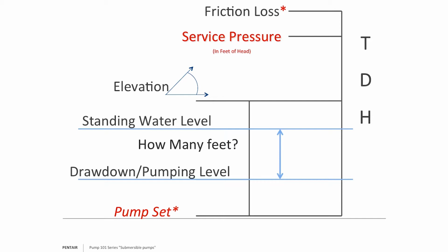Always take it for the worst case scenario. If at 54 gallons per minute the drawdown was 15 feet, I would say even at 12 gallons per minute, I would be anticipating 15 feet of drawdown. Some guys will argue with me, but I always say you got to CYI, cover your interests. Okay? Make sure you have all your bases covered.